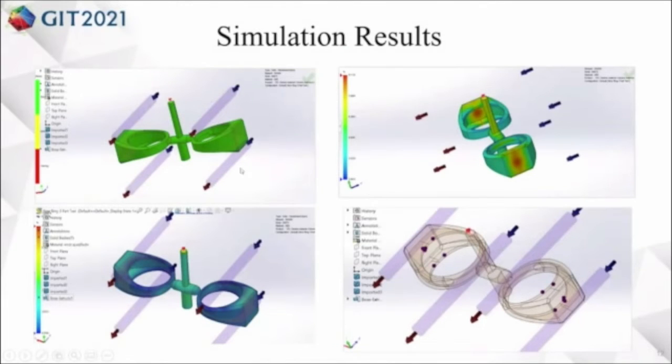Here, the result from the simulation can show you whether the jewelry item will fill completely or not, or where on the jewelry item porosity may occur, or where an air trap can happen. With this kind of information, we can prevent defects before going to the production process.